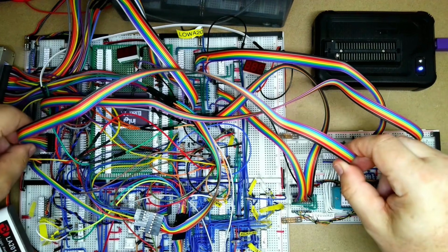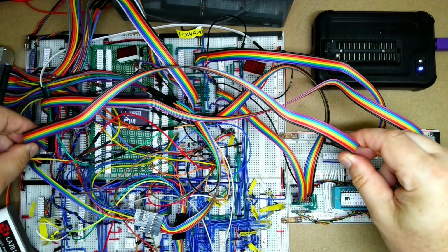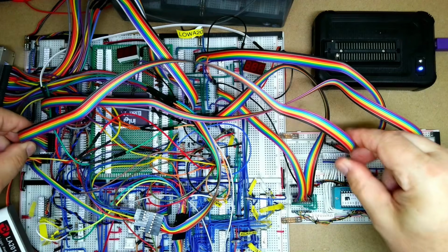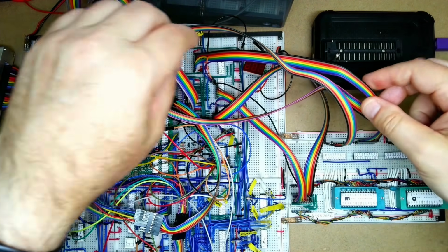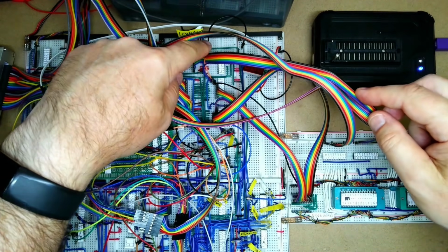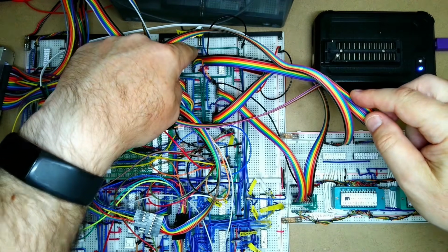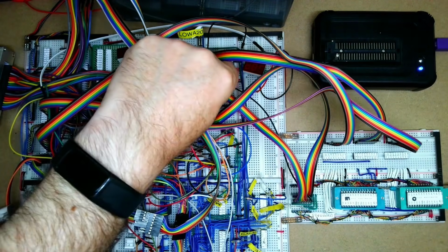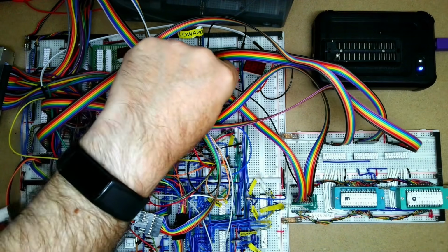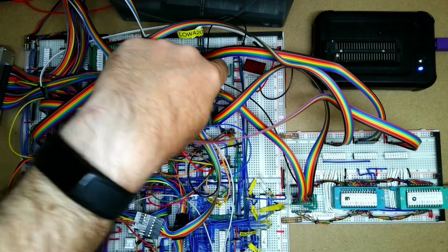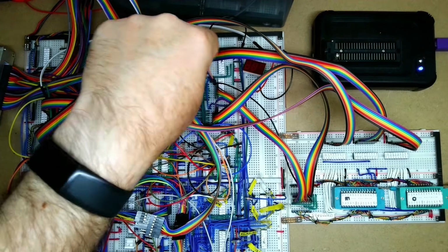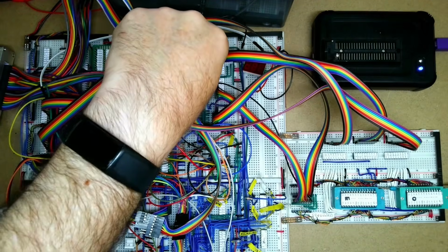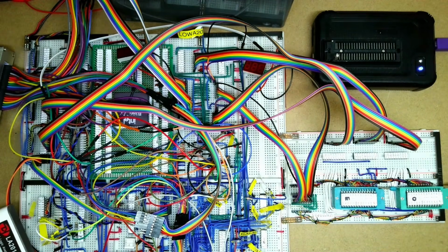And then this is the lower 8-bit, so this is SD0 to SD7, and then this is our latchable lines, and the latchable lines go over here. So there's 2 blocks of 3 here, and the block of 2 goes into the SA16 and LA20 that comes from this buffer here, which is how the original DeskPro and the PC AT maintain compatibility with old 16-bit software that didn't know about the memory above 1 megabyte.